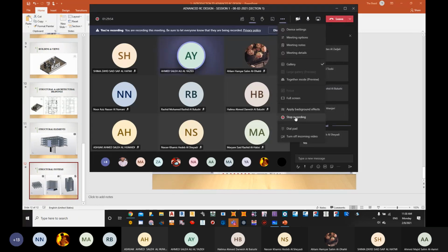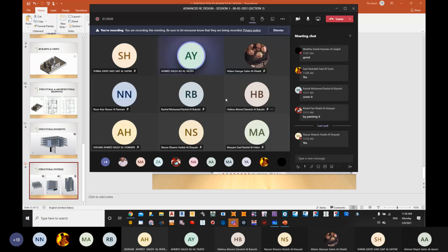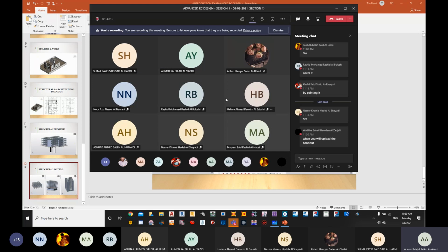Mister, you said second system. Okay. They are using flat slabs in residential and commercial. Yeah. Why is it commercial building? Why is it using only flat slabs? Flat slab will give you a longer span between columns to columns. So avoiding the beams, a lot of beams.